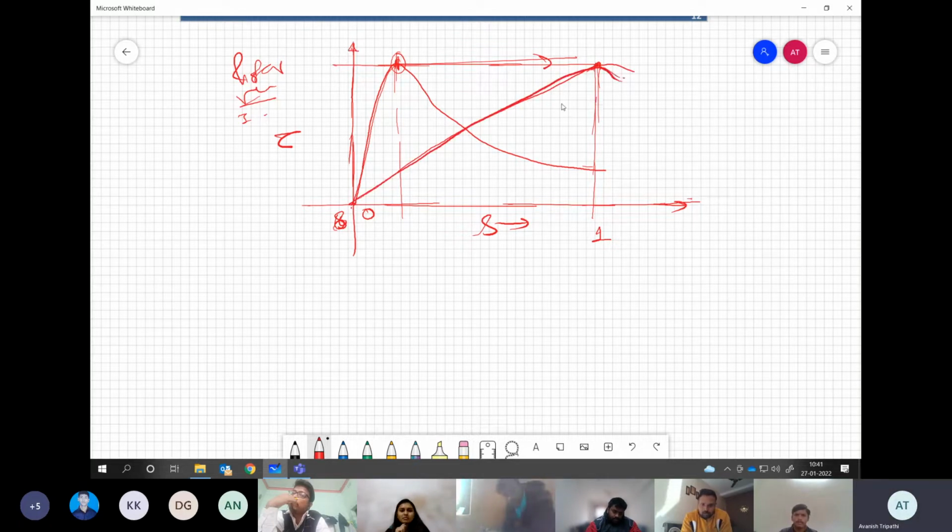Correct? Now any resistance value in between will give better starting torque than what the motor originally had. If you try to insert anything more than this value we have computed, it will be useless because your starting torque will further reduce. It will not increase.